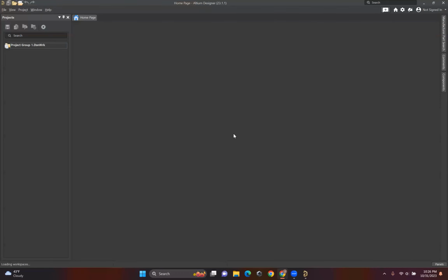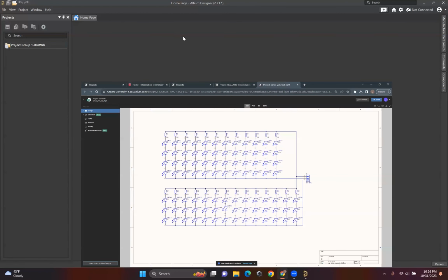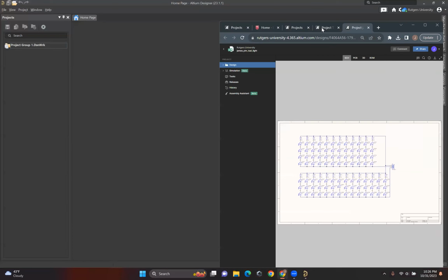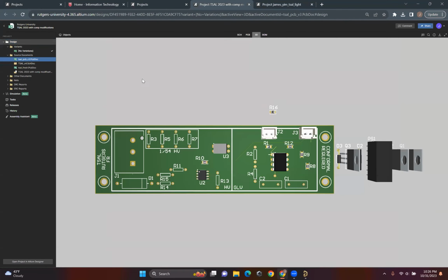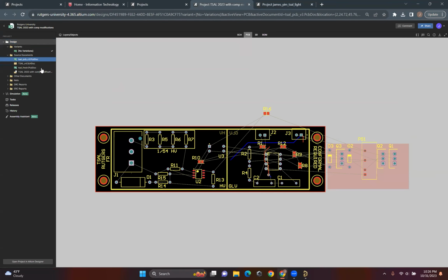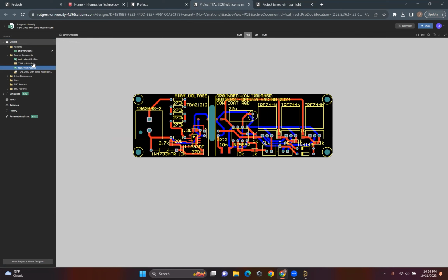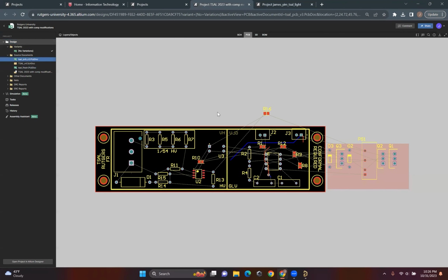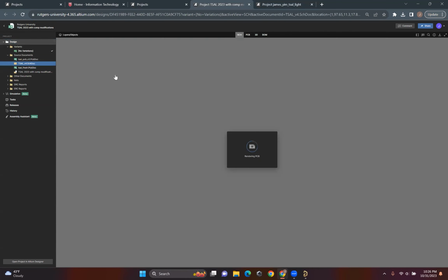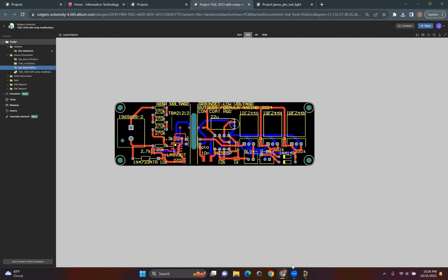And like you saw on the last board in the preview, while that's loading up, I'll show you guys this. You can see this is the schematic. By default, it's showing this board, which obviously isn't complete. It's just on the source documents. You can make different versions of the same schematic, like different PCB designs of the same schematic. So this design and this one are both based off of this schematic, but I just made a new PCB document within the same project.